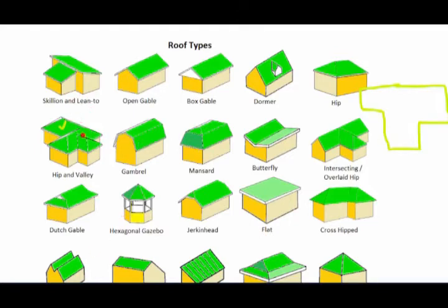As I mentioned, if you are going to have a gable roof like this one, 45-degree roof plans, always keep in your mind that you have to work with 45-degree issues in all the corners in order to design your roof. And this 45-degree will let you create such kinds of forms that will support you in designing the roof plan. This is the easiest way to show. From each corner, 45-degree you will take out, and this 45-degree will help you to design the roof plan from here as well.